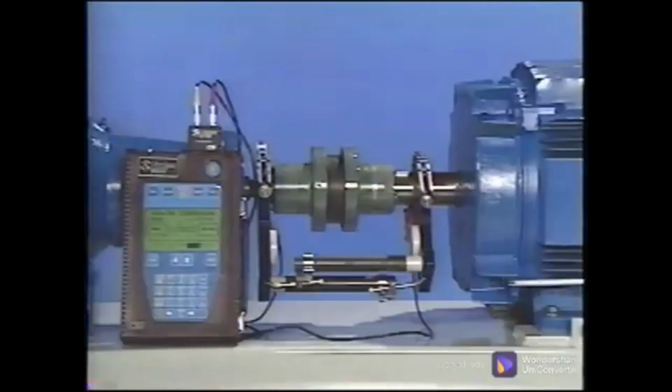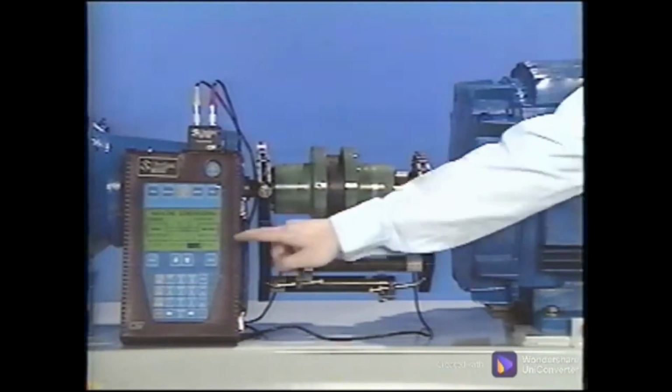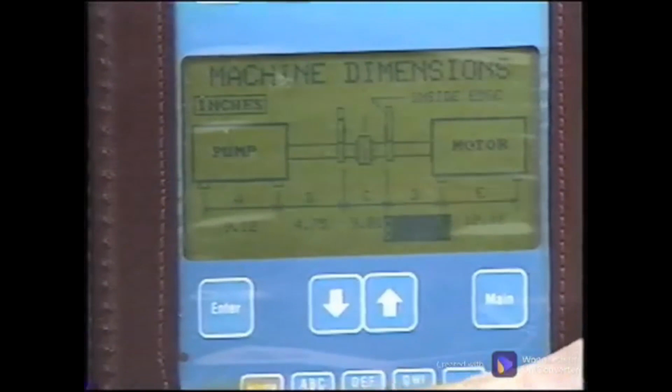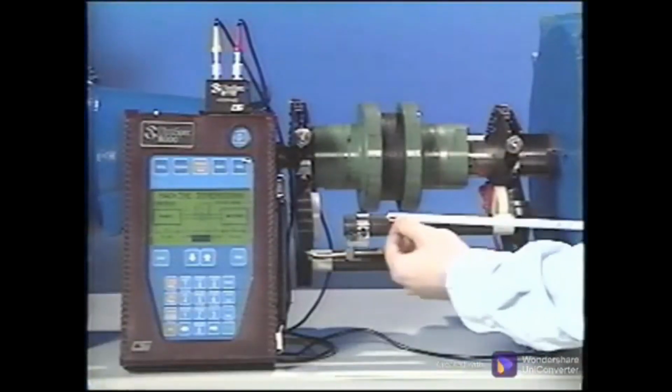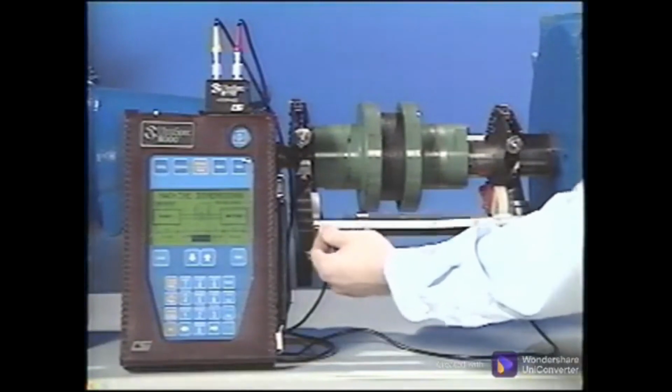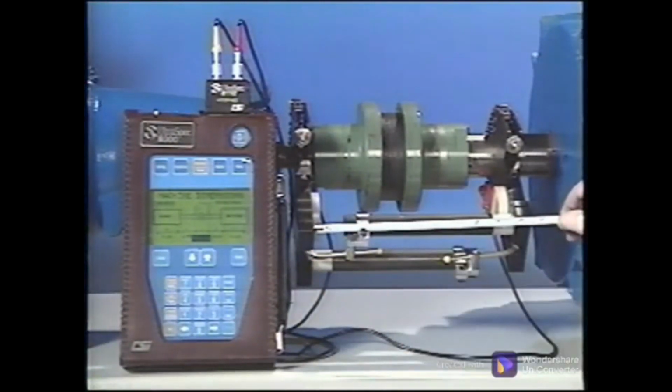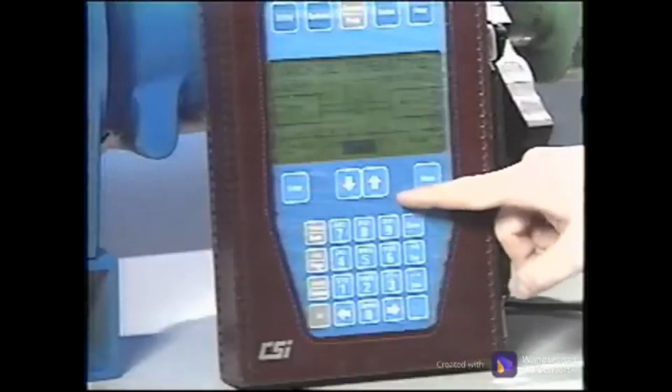Distances between feet and from the feet to the face of the heads are required for accurate calculations. The most critical distance, though, is the distance between the faces of the heads. All these measurements need to be as accurate as possible, so it may be necessary to use a plumb bob to measure the distance from a foot to the face most accurately.